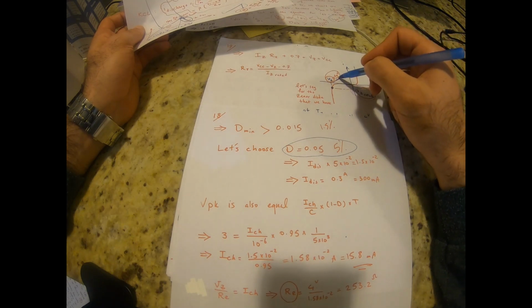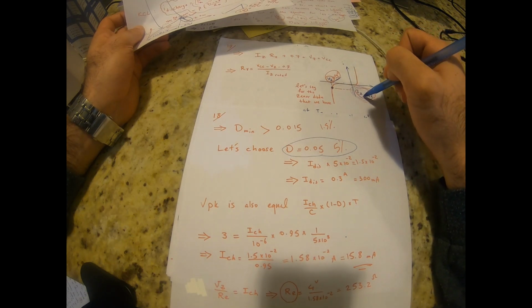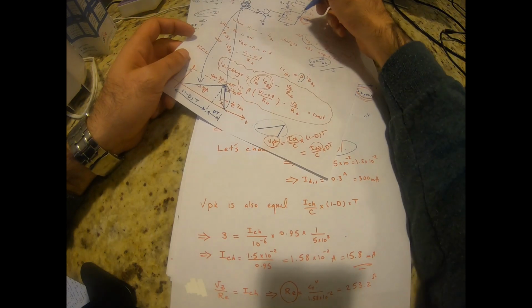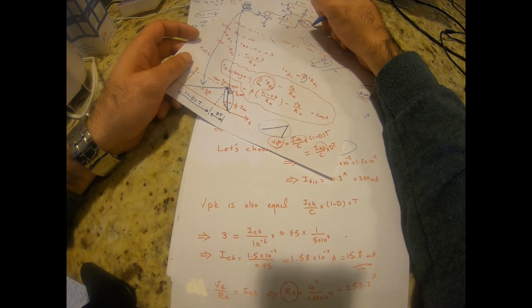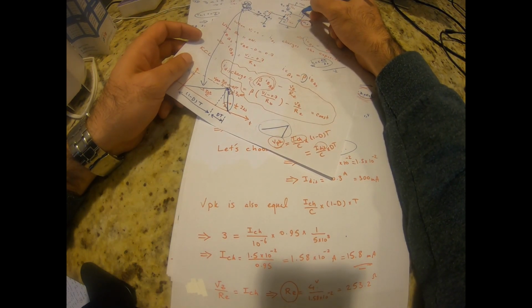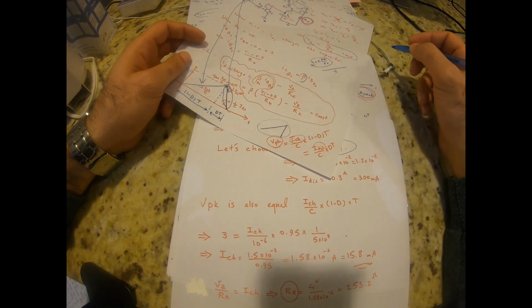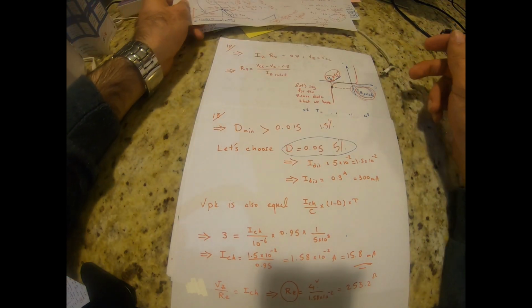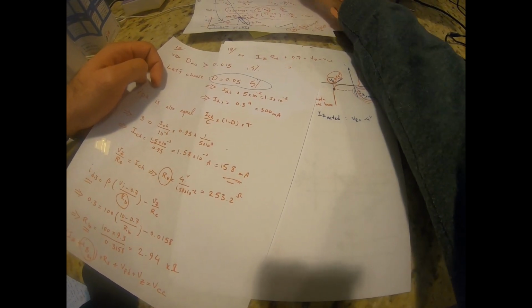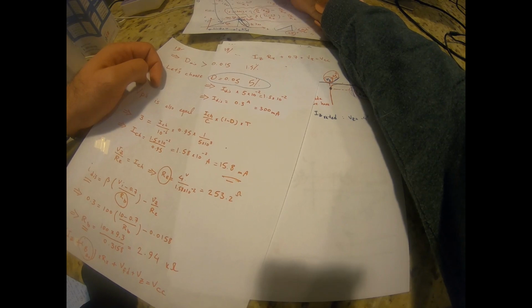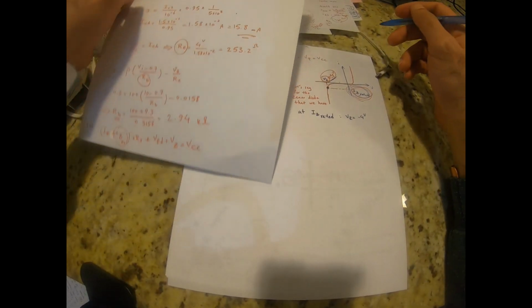Once you find that based on the data sheet, you can design your RX so that it would satisfy the rated Zener current going through here, right? So this is the part that's done here. It basically writes a KVL here because we can assume that the base current is almost zero.